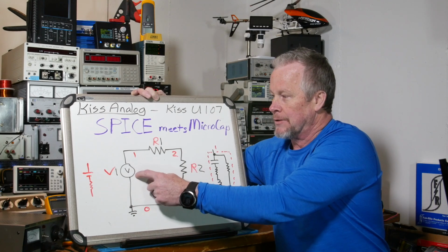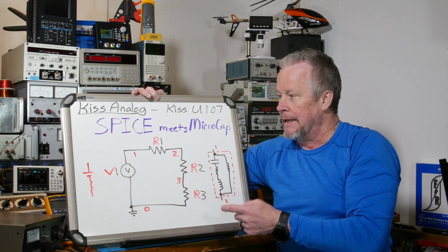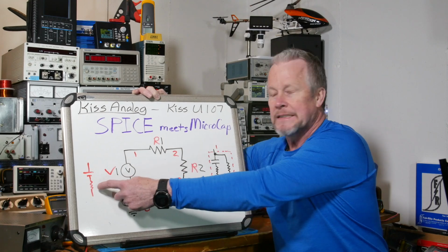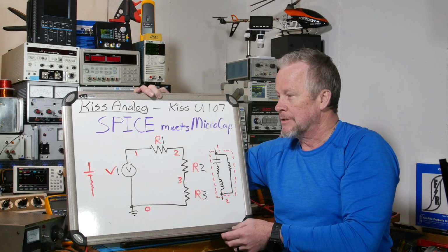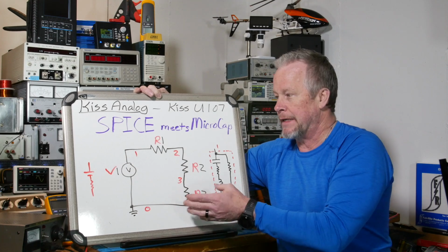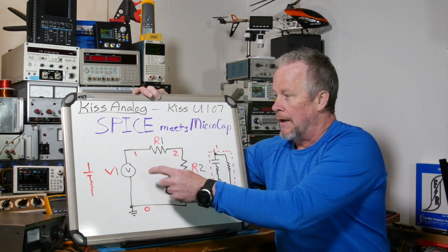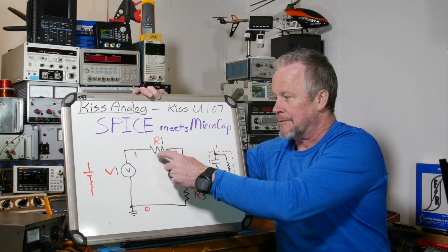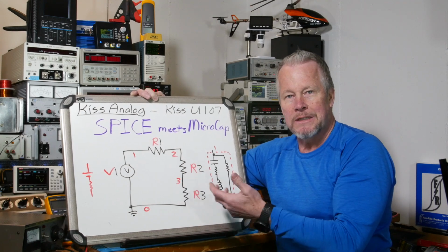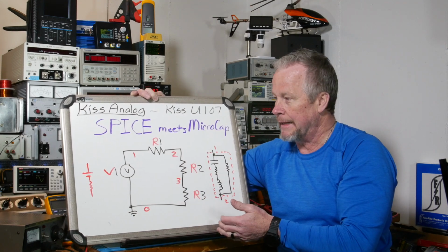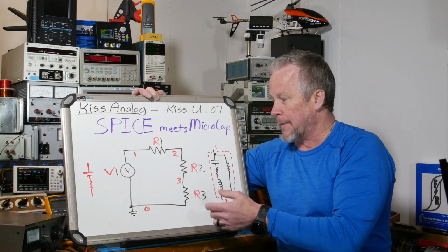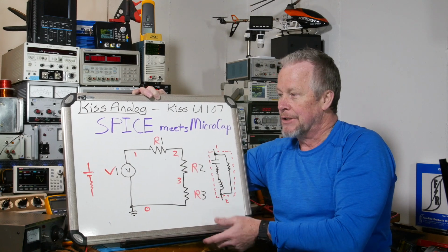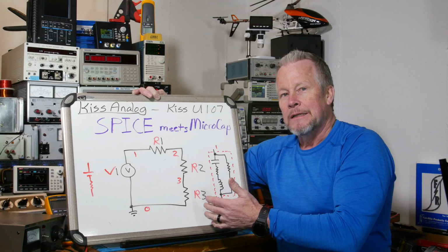So really, this voltage source has some internal impedance in it, and it can only put out so much current. So it's got a current limit, plus it's got a source impedance limit to it. So that's another real life example. So you have to consider those things. Often when you put a voltage source, you might just start off with that, knowing that you have some resistance. Maybe these are K ohms, and you don't care if there's a couple hundred milliohms or something like that. But then in another circuit, the one I had before where we had a capacitor and we're trying to charge it, maybe we do care about that. So sometimes you do care, sometimes you don't.